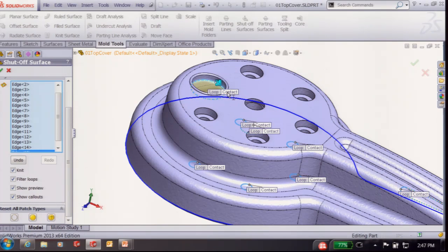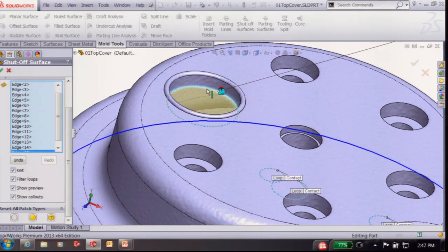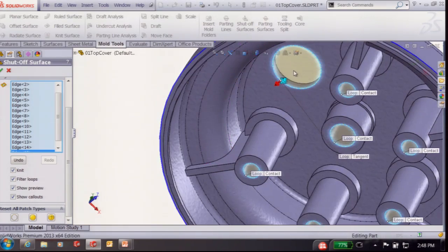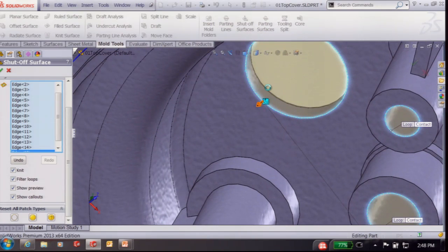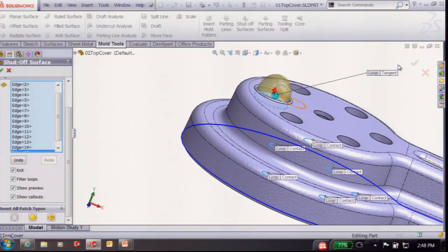If I select tangent, it tries to pick one of the faces that it intersects and makes it tangent to that face. And there are controls for up or down, or which face we're going to work with. If we want localized control over that, like let's say this one, we can just click on the flag and it'll change to the next one. I guess double click, and that made it tangent. And it made it tangent to that bottom face, which is under there. If I select on that arrow, it switches the tangency to the upper face, and it sort of domes it out.